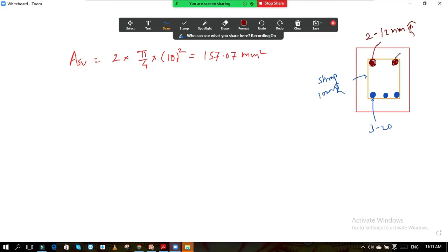Minimum it is 10 mm actually. As per the code, what code says that you should provide at least 2 bars of 10 mm diameter at the top. But here for our safer side, instead of 10 mm diameter, we will go for 12 mm diameter. Okay. So I hope now you understood these things. So here I will write, also provide for earthquake proof resistant structure. Okay, provide 2 bars of 12 mm